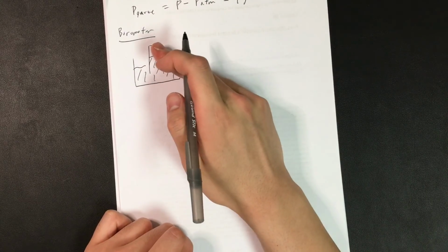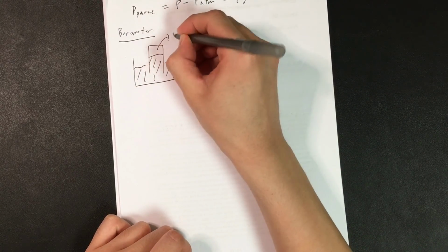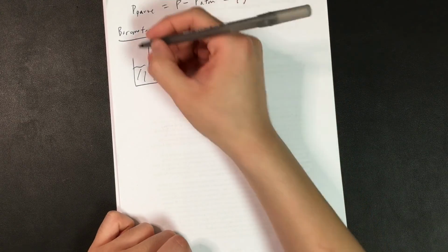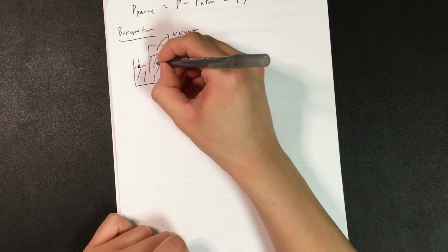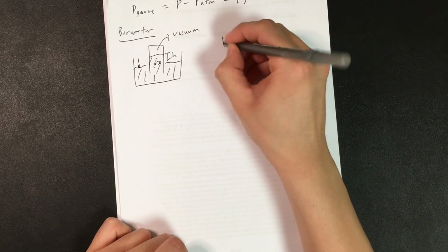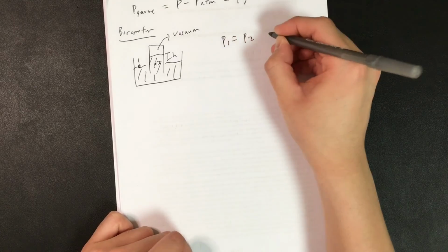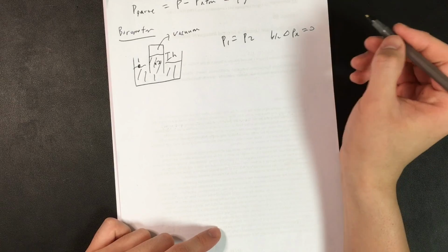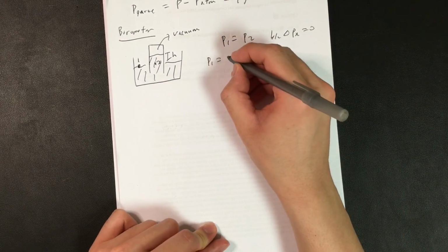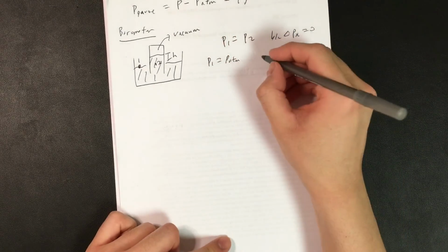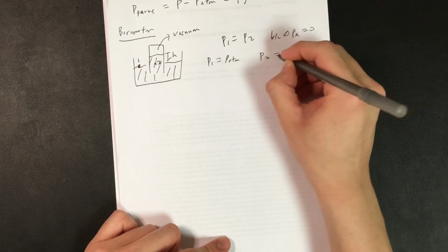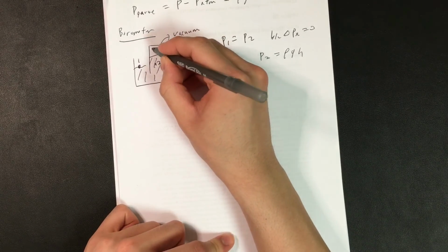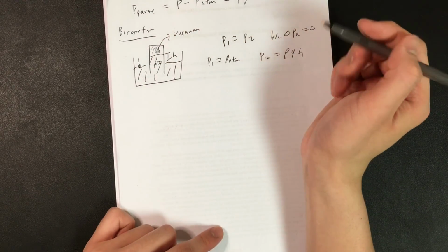So inside this device, it is filled with water, and this is a vacuum space. If I call this height h, and call this point 1, call this point 2, then pressure at 1 equals pressure at 2, because change in pressure along the horizontal direction must equal 0. But pressure at point 1 equals the atmospheric pressure, and pressure at point 2 equals rho gh, because in here, since this area is vacuum, there is no atmospheric pressure.